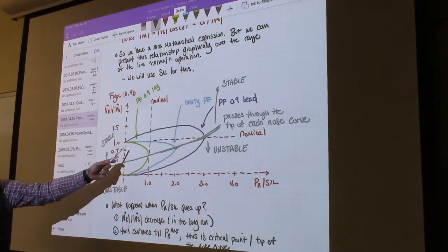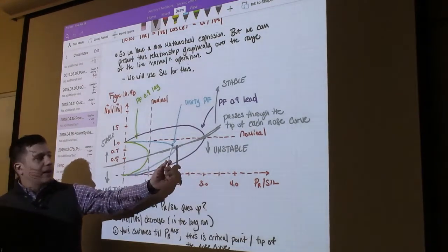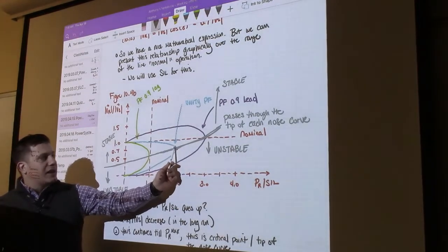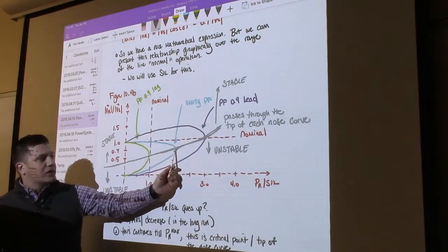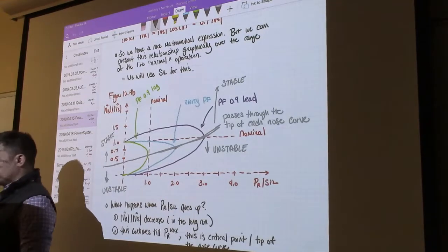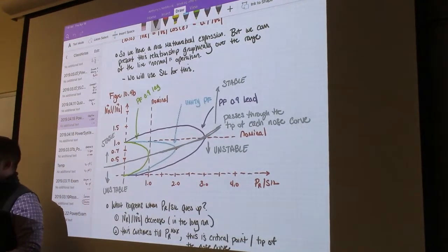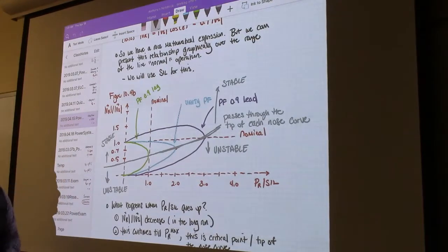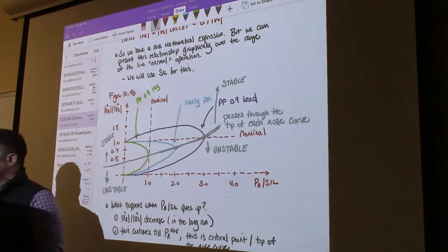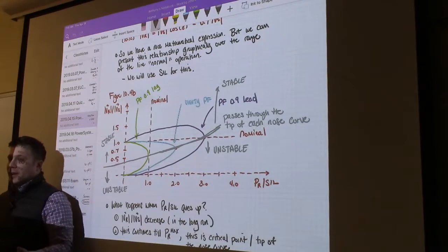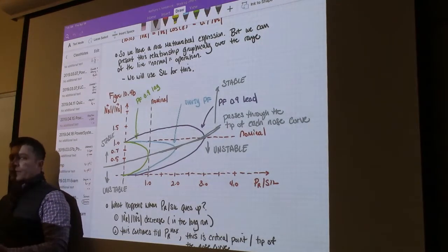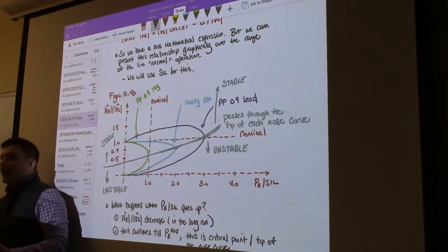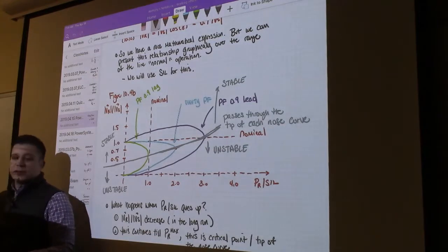However, there are a lot of things we can take away. One is seeing the increased rate of change in the voltage magnitude downward as our loading increases. But that's something you expect to see with any instability: as you push it further and further, once things start to run away, you would expect that you're getting close to instability.